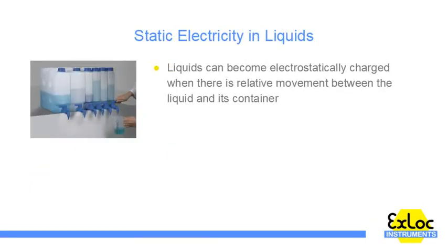Static electricity in liquids. The following requirements apply to common flammable liquids such as organic solvents, hydrocarbons, fuels and alcohols. Liquids can become electrostatically charged when there is relative movement between the liquid and adjacent solids, such as the pipe it is flowing in, or if there is a second component that does not mix, such as oil in water. Spraying or splashing of liquids can also create a highly charged mist or spray.